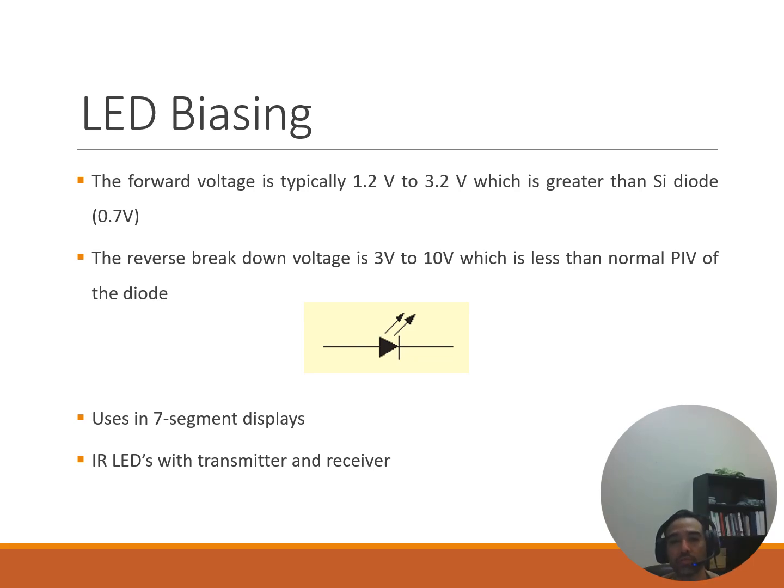The reverse bias voltage is also on the slide. Good question. What is it? Well, it says on the slide about 3 to 10 volts. What the heck does that mean? Just like you can't push open a door the wrong way. You could, but you'd break it. Diodes only work when electricity flows in the right direction. If you try to push electricity the wrong way, we call that reverse voltage. For LEDs, this reverse voltage limit is between 3 and 10 volts.